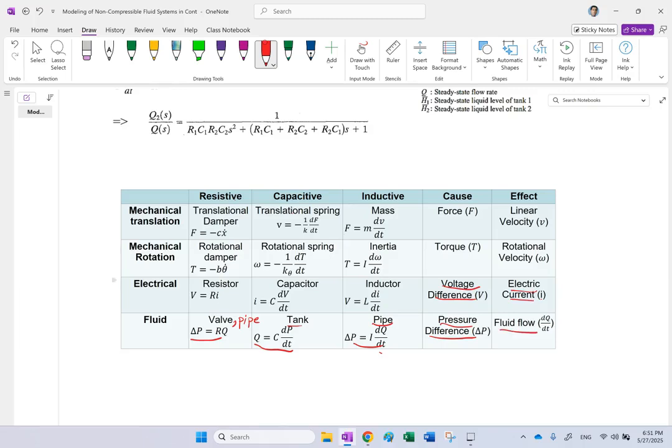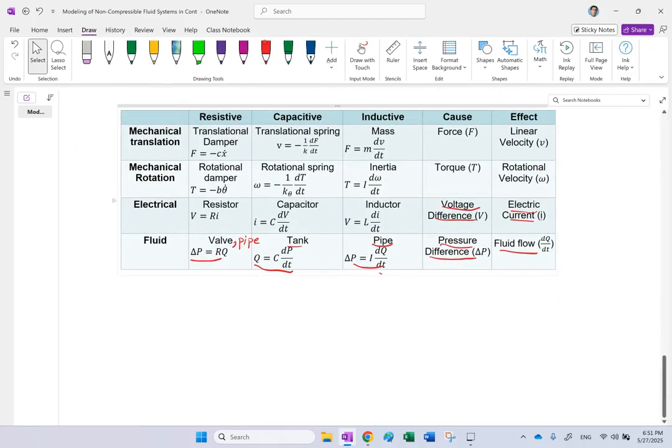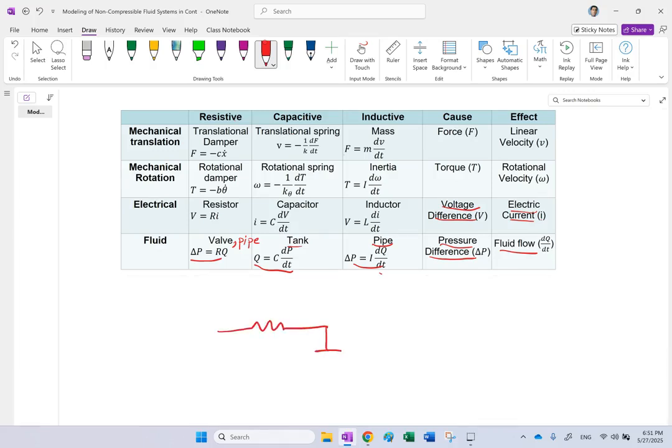Good. Now remember, in electric circuits, we had two important laws which were the essence of electric circuit analysis. One was the Kirchhoff voltage law, KVL, which said that if you have, for instance, a resistor here, a capacitor there, or anything else, and this is some voltage, if you go around any loop, the sum of the electric voltages across the loop equals 0.